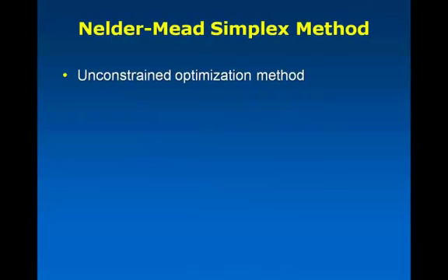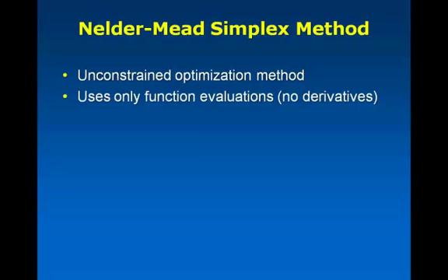and talk a little bit about the actual way that we do this. So we use the simplex method for doing this parameter search. This is an unconstrained optimization method, and it works well for any number of parameters that you want to do the optimization for. Certainly it works better when there's fewer parameters to optimize, but there's nothing stopping it from using more than 2 or 3 or any number that you like. It uses only the function evaluation, meaning that we don't have to run a lot of simulations to find the values of derivatives of all of the relevant parameters.